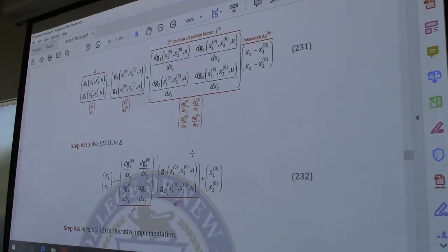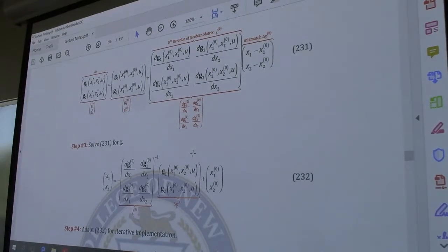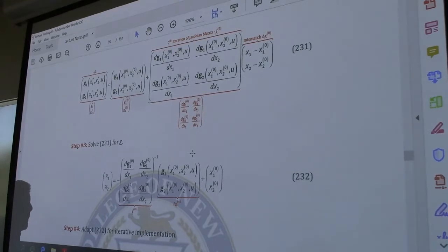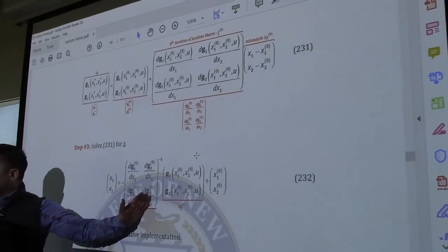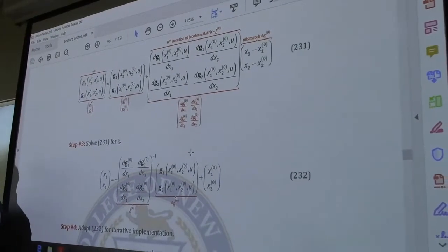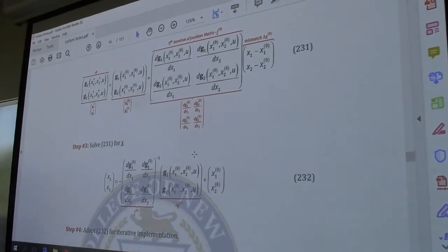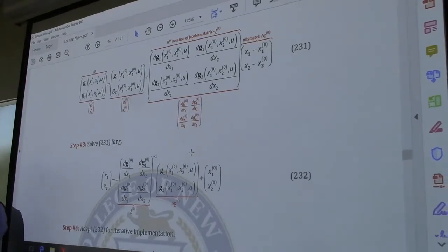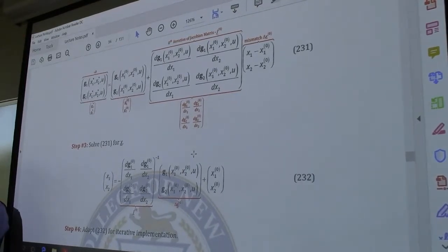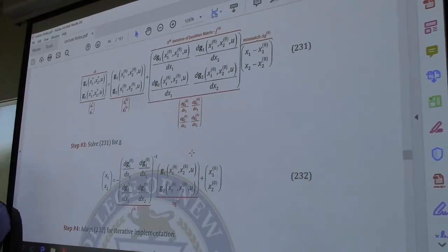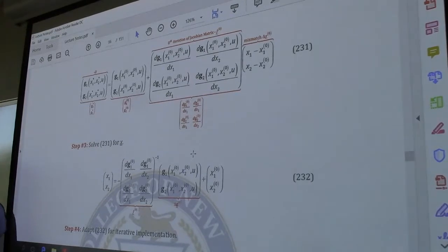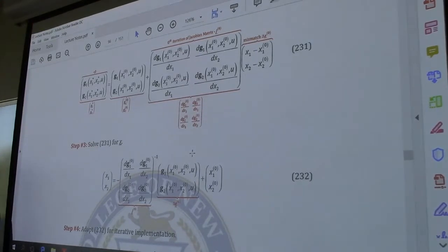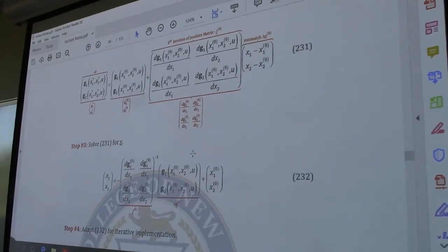And so using or implementing the Newton-Raphson method is mostly just, okay, I know this is the form that I need, which is a little bit different than the Gauss-Seidel, right? With the Gauss-Seidel, you have to formulate each bus's equation a little bit differently, depending on how many lines are connected to it and whether it's a PV bus or a PQ bus. But that doesn't come into play for Newton-Raphson.